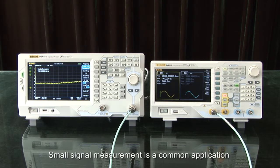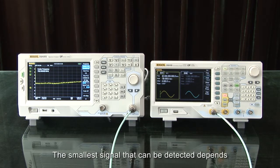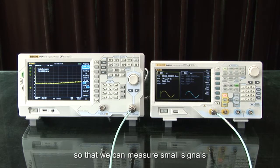Small signal measurement is a common application for a spectrum analyzer. The smallest signal that can be detected depends on the displayed average noise level, or DANL, of the instrument. This video will show us how to reduce the DANL so that we can measure small signals.